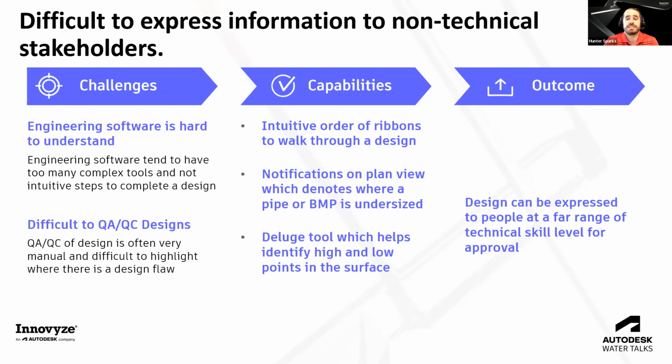And once the analysis is done, you can actually run a simulation of the rainfall coming through your system. And in an animated nature, it's going to show you where that HGL is in your pipes, in your stormwater control structures. And it's even going to give you notifications where you have surcharging, flooding, overtopping over your stormwater control sections.